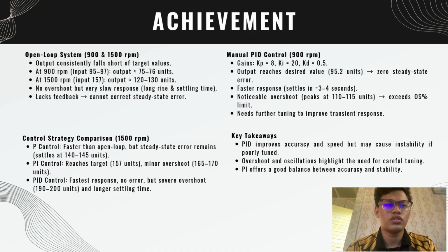PI control offers a good middle ground, eliminating steady state error with less risk of instability. So careful tuning is critical, especially when the system needs to meet both accuracy and stability requirements.